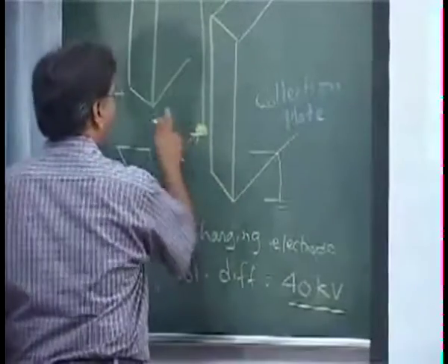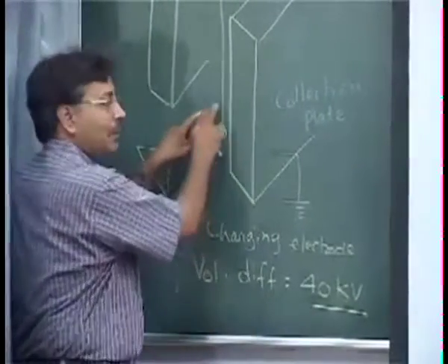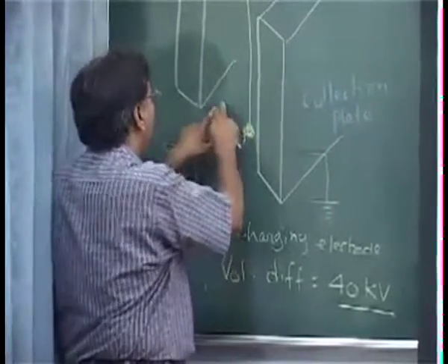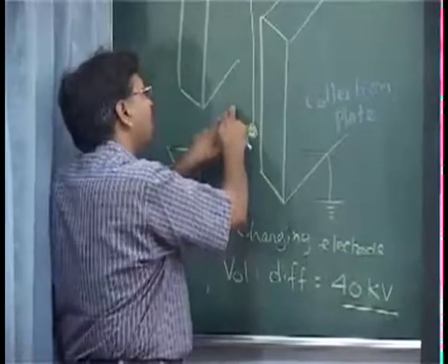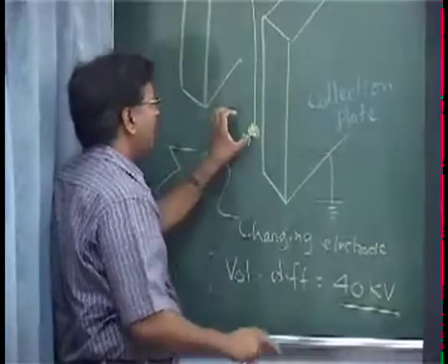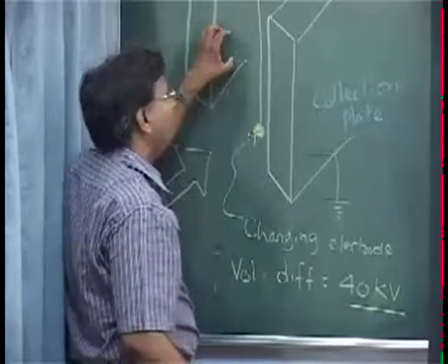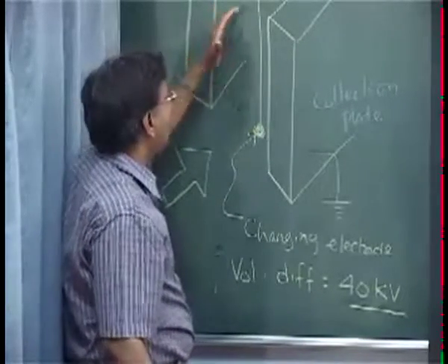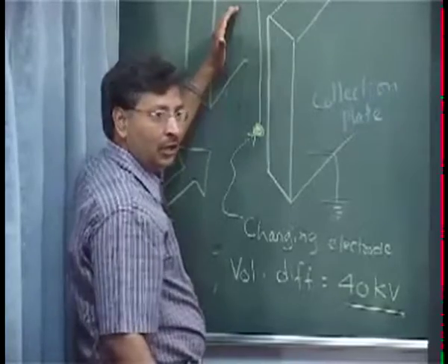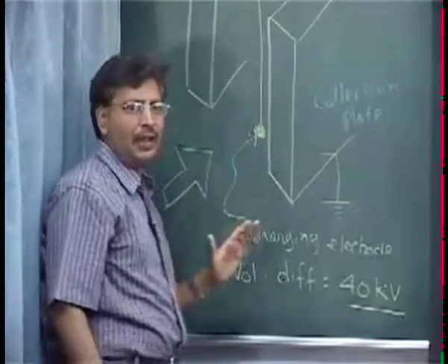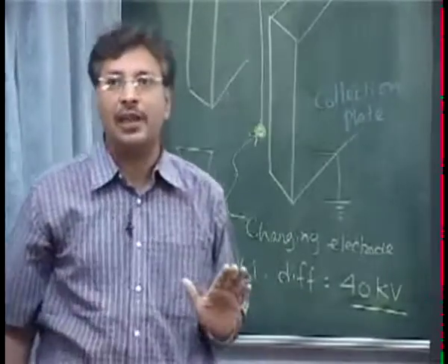The electrons have to go towards the plate, but on the way more electrons become available, and they sit onto the particles, and then the drive continues towards the plate. As a result, all the particles start moving from wherever they are back to the plates. The moment they hit the plate, they will discharge and stick to the wall. So this is the mechanism, this is how this happens.